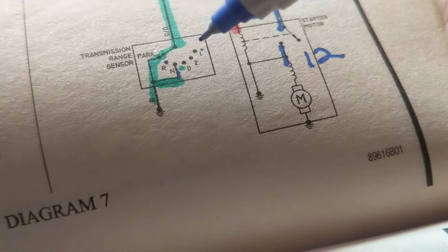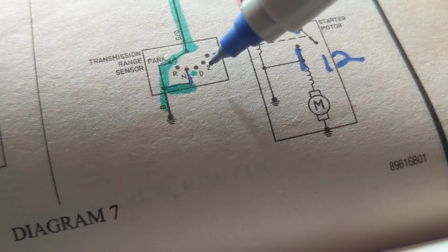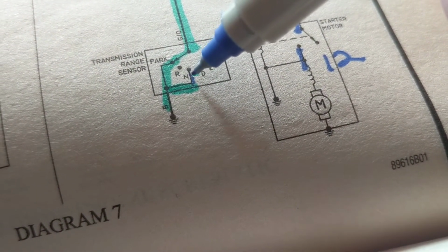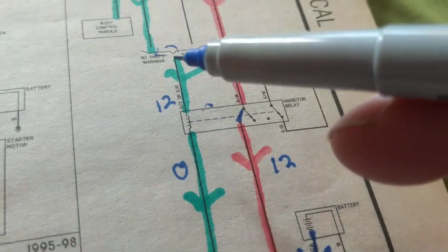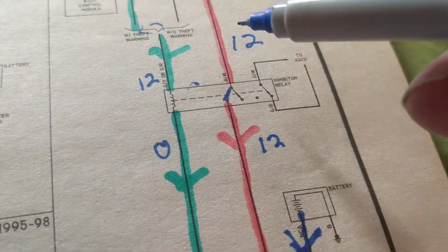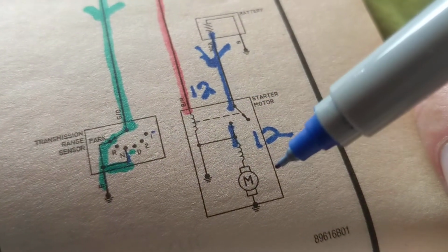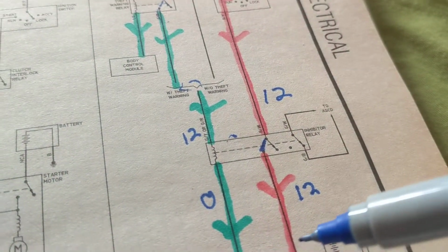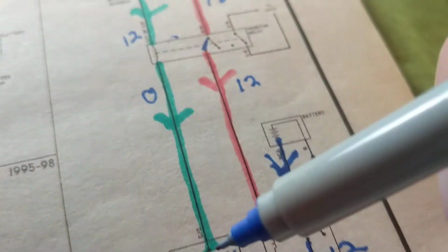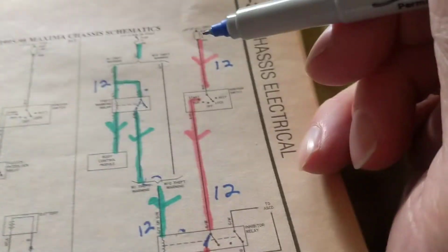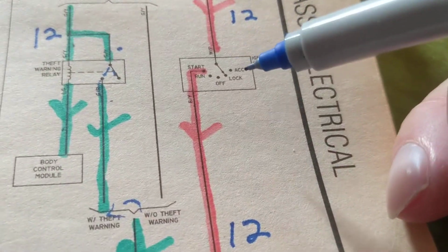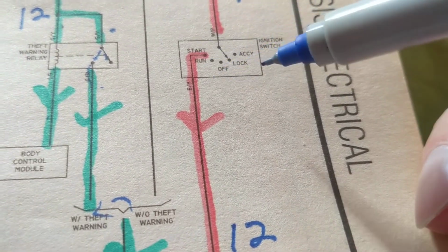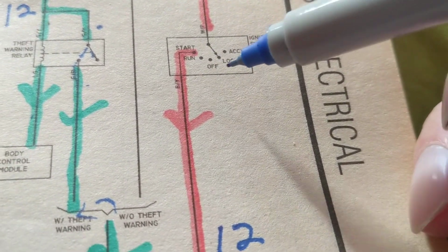And that's why it's there. If you are in any gear but neutral or park, you cannot activate the relay. You cannot start the starter. That's how it works, if you ever wondered. Fine. We just went through this part of the circuit. Again, we just looked at the symbol. Same thing as before, except different names.